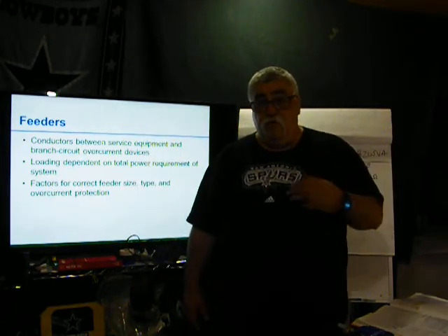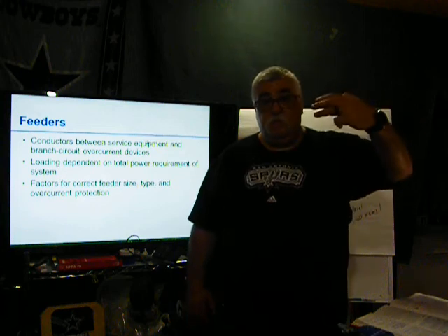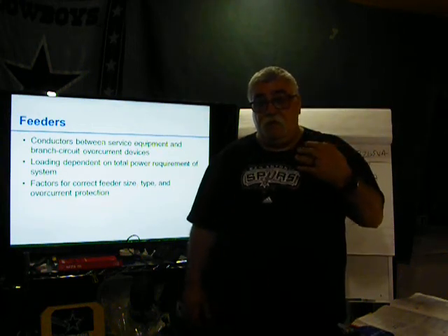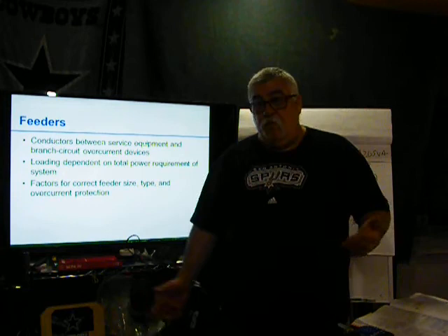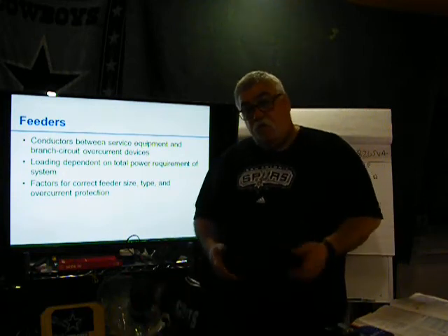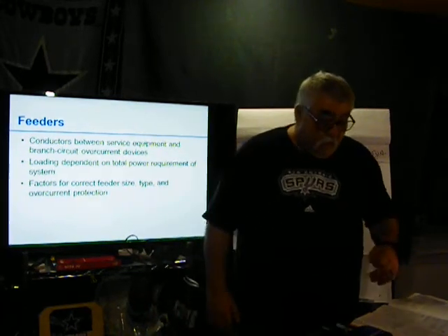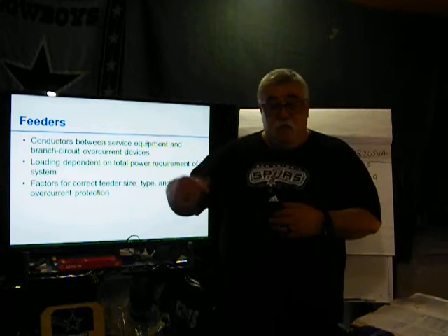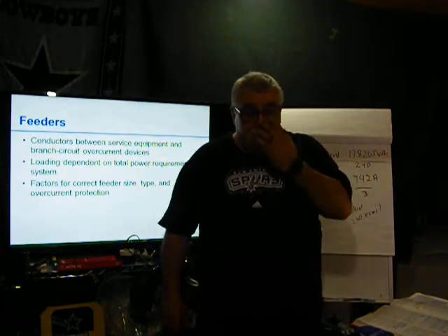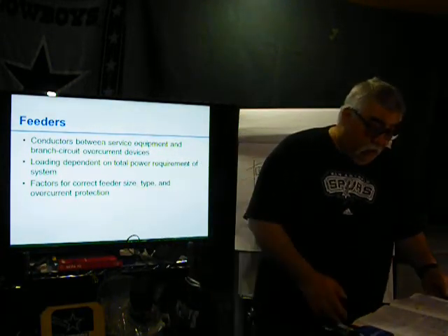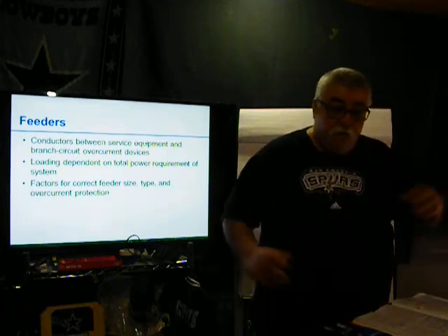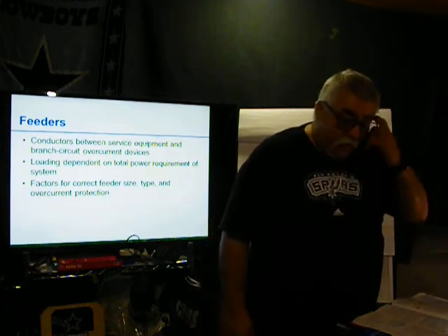Okay, so they don't bring a neutral in. They just bring 3 hots, and we pick up the ground off the grounding. Now we set up our own transformer and they take it in. And then now we have the neutral. That's where we get off the transformer. That's where we get our grounded wire out of. So we go from a delta to a Y, 120/208 3-phase.